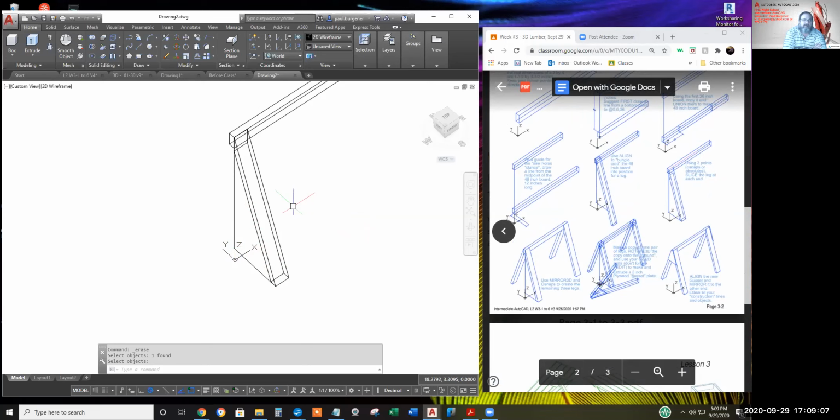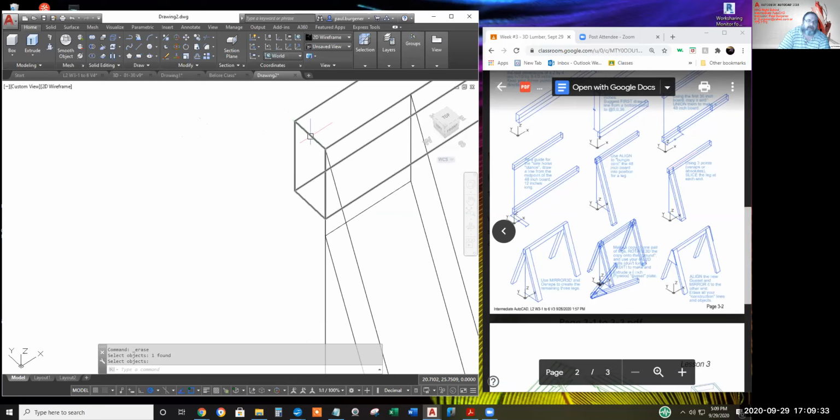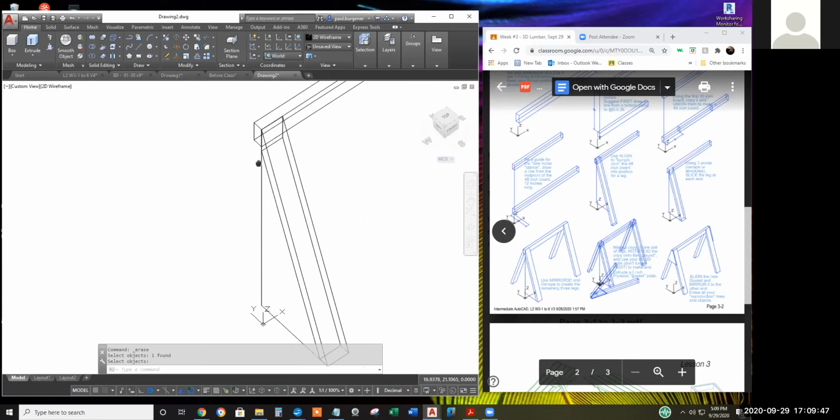So Dan, I'll take your advice and specify a 3D mirror about a XZ plane. No, you can't do that because the 2x4 isn't centered on the XZ plane. That would be 3/4 of an inch off. Well, I'm with you, but eventually it'll say specify a point. Oh, is that how it works? If I set it there, then it would really be a plane parallel. Oh, okay. Let's try it. Oh, yeah, that's interesting.